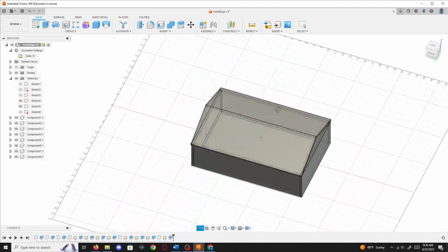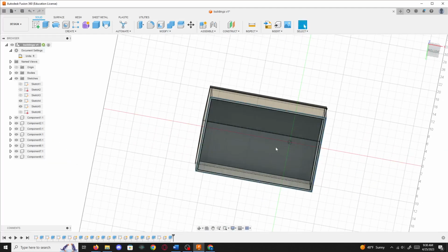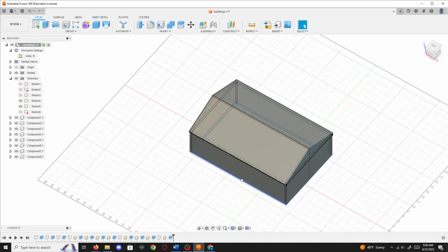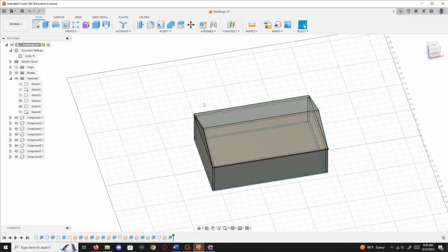That's enough for now. I will release another video that shows how to put doors in here and add internal walls. But the short version of that is create rectangles inside of here and extrude them as walls, and create sketches on your walls that you can push in to cut out windows and doors. Alright, thank you for your time, and there will be more later.